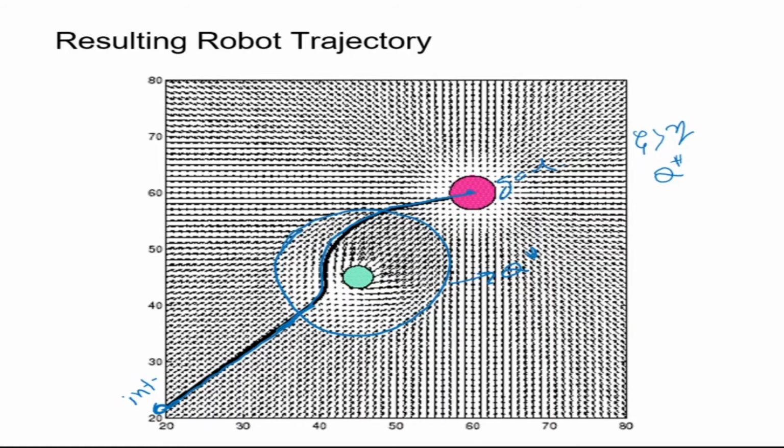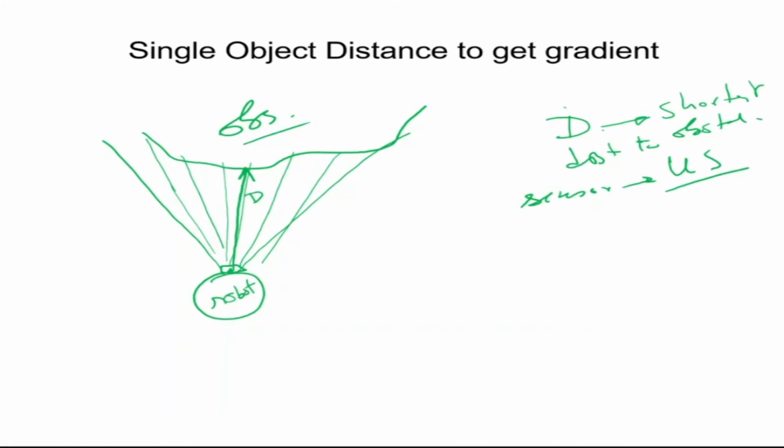Okay, so this explains the potential field method, how it works, how potentials are assigned, and how the negative gradient of the potential is followed such that the robot can reach the goal. Now what we talked about is number one is local minima, number two is distance and gradient. Suppose I have an obstacle here like this, that's my obstacle.